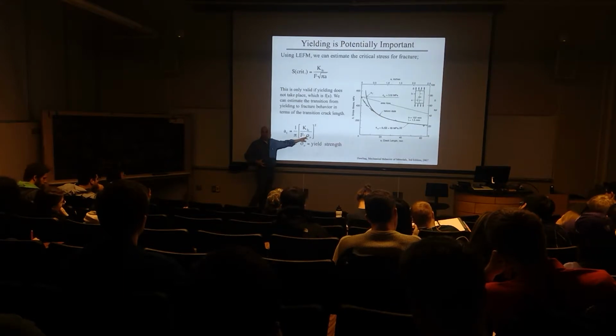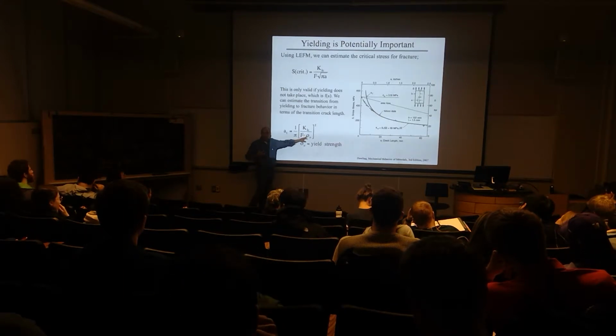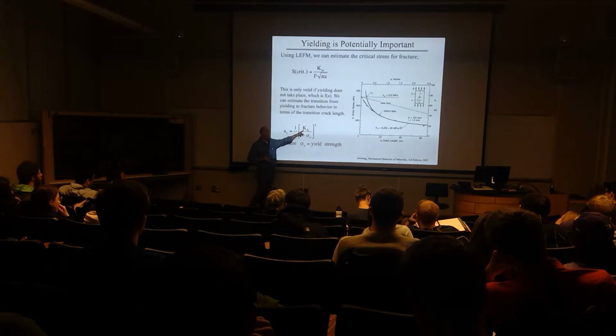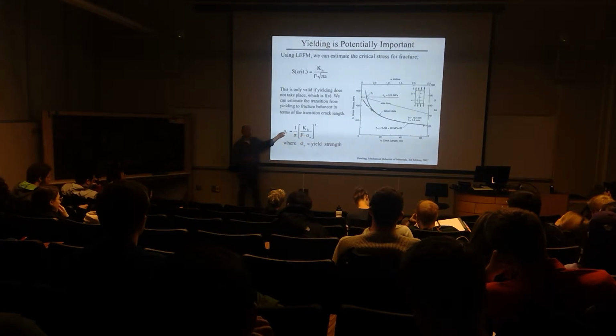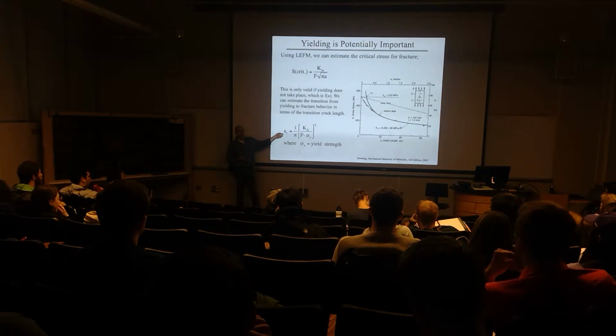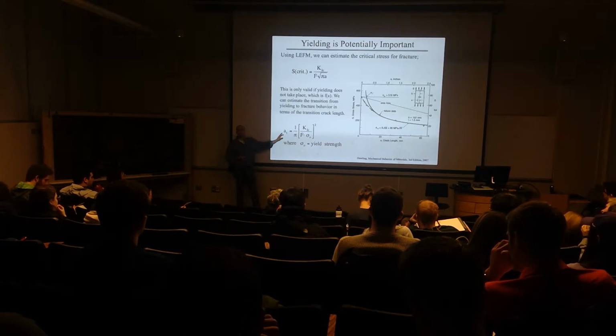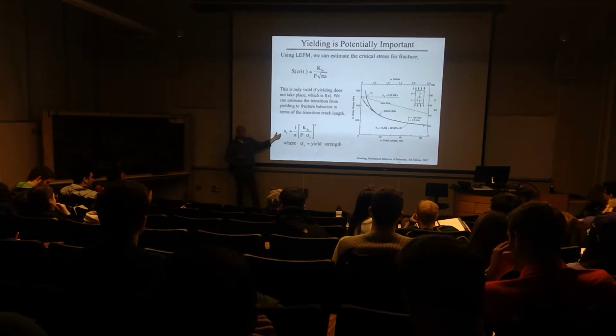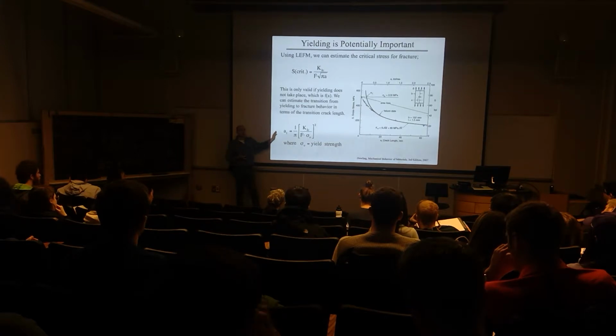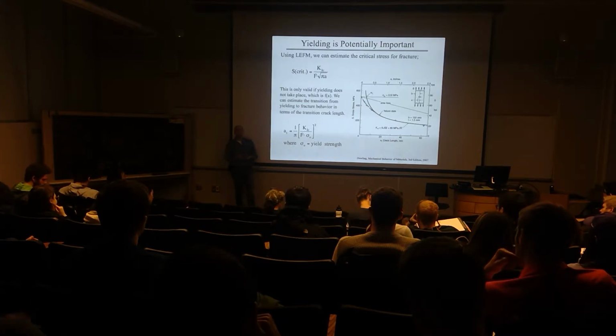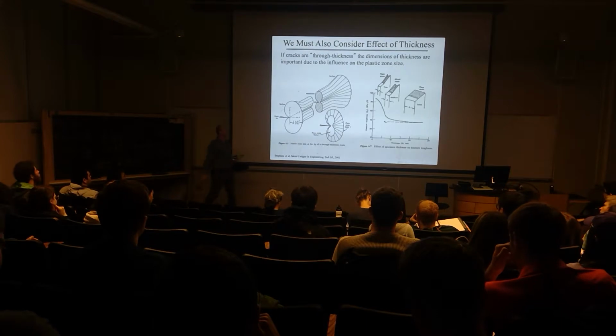If I heat treat for strength, thinking that that's the major mode of failure, and I forget about fracture toughness, what did I do with the transition flaw? It drops substantially. And then what does that mean, that structure, how will it behave? Looks the same, but it will be much more sensitive to flaws, and much more likely that flaws will dominate its behavior rather than yielding.